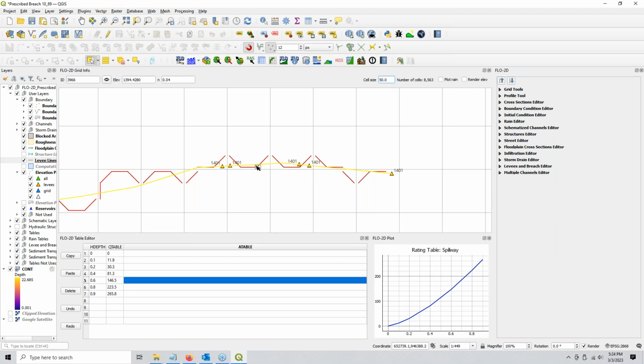So that means that each of these are about 0.41 or 0.42 times 50. So these are about 20 feet long. And so we want about 100 feet to represent the crest length of our spillway. So we need about 5 of them.